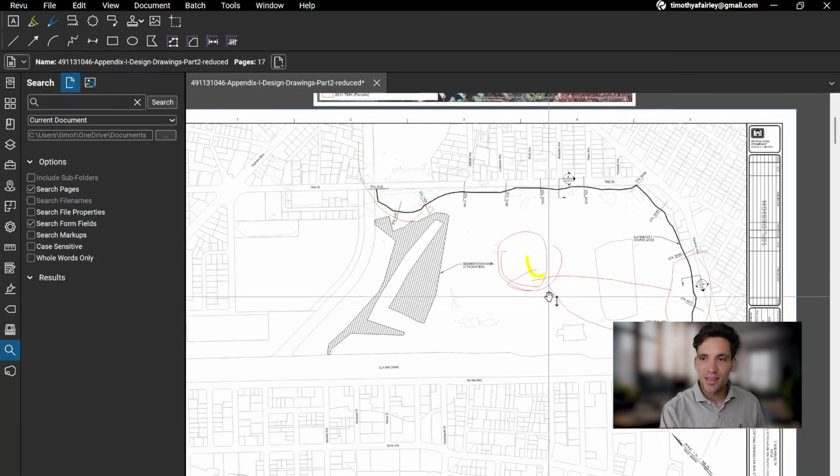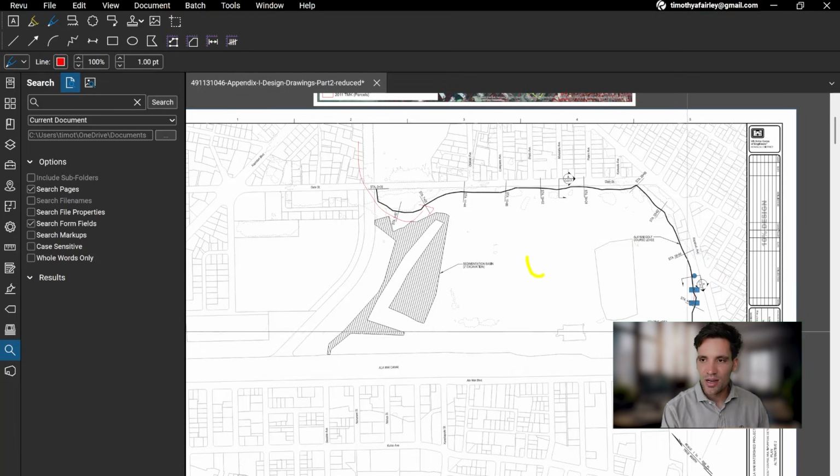So the benefit of this would be, say you excavate, this is probably explaining this in a really complicated way. Say you've excavated that, and this section, these couple of 100 meters, are ready to start placing material. You could start excavating here, and the trucks could go and directly place it here, in which case you're not actually double handling.